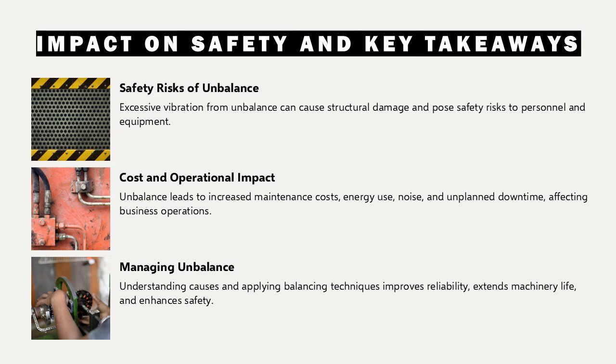The impact of unbalance extends beyond mechanical wear to include safety, cost, and operational reliability. Excessive vibration can lead to structural damage, fastener loosening, and increased noise levels. In high-speed machinery, unbalanced forces can become severe enough to cause catastrophic failure, posing risks to personnel and surrounding equipment.